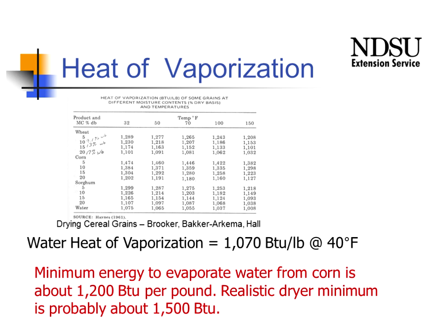Now, we've had dryers that have had claims as low as 1,100 BTUs to take out a pound of water, and I've challenged that that's just not going to be practical or realistic. In conversations I've had with some of the dryer manufacturers, they seem to be pretty much in agreement that this 1,500 is probably the optimum that we could obtain.